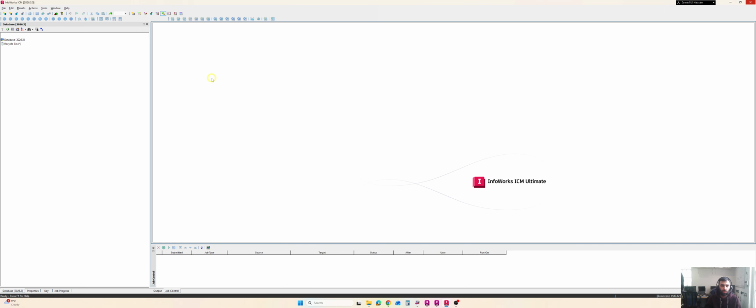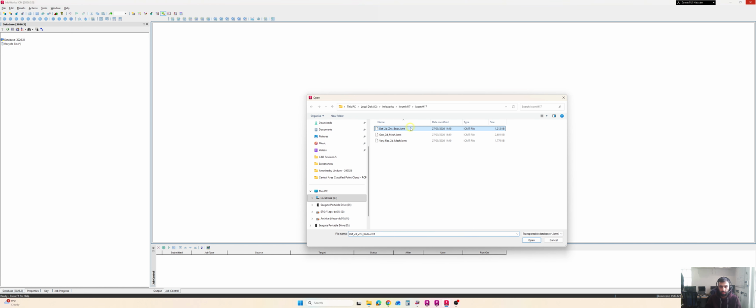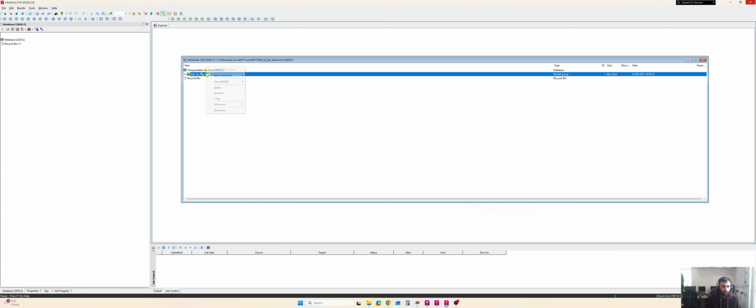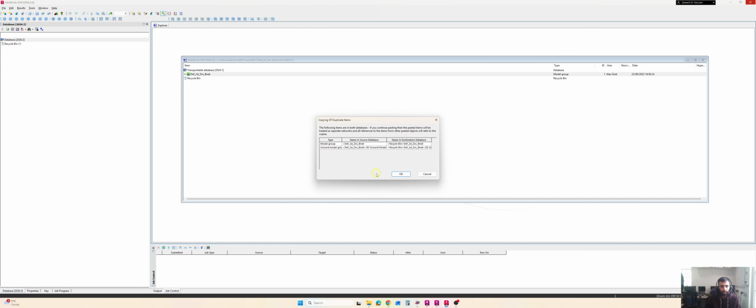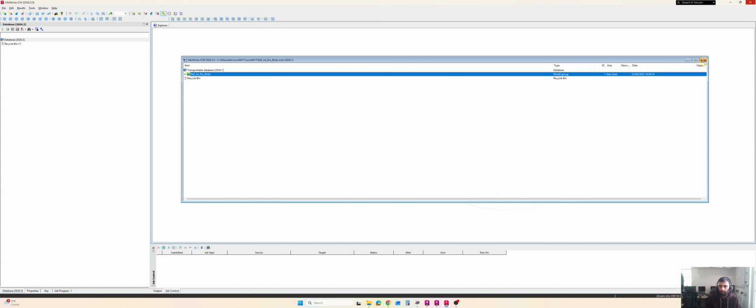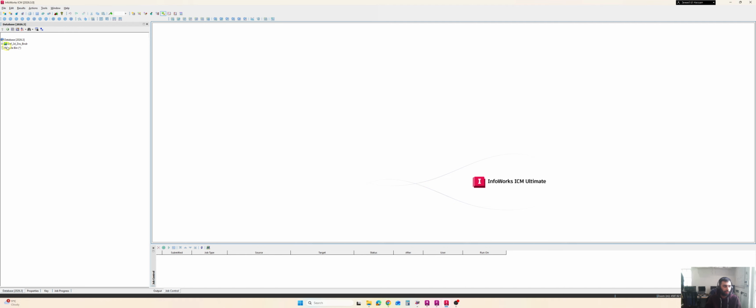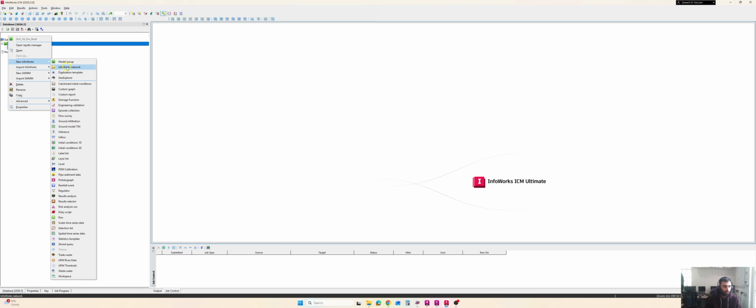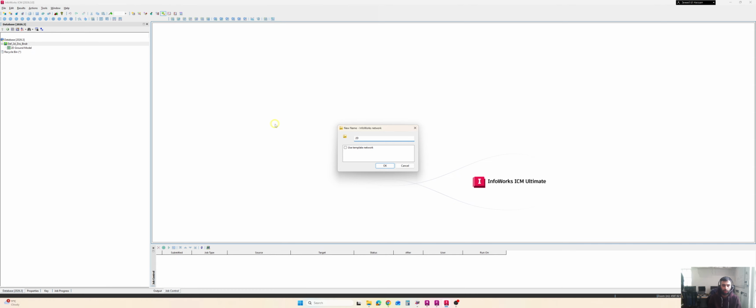In today's video I am going to show how we can create a 2D river area, 2D river zone and then the boundaries. So I have already opened my InfoWorks and I am just going to import the drawing that I have. So I will copy this model into my model and then just click OK, copy the ground model and just close this one, double click, and to see I have this ground model and I want to create a new network 2D river.